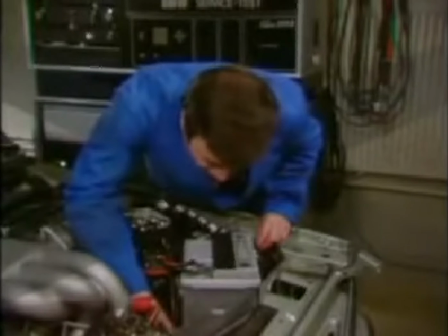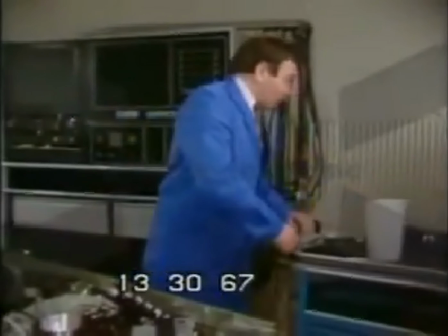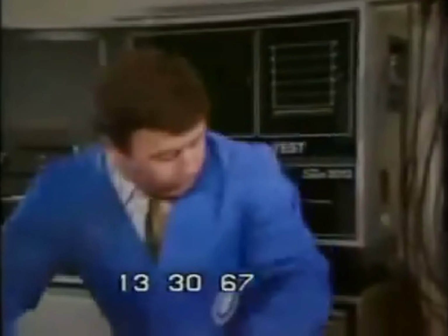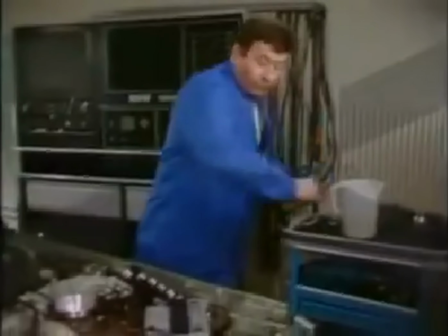Then we check the fuel flow quantity. We want to know if enough fuel is being supplied to the mixture control unit. The tools required for this task are this petrol pipe and a measuring container of about 2 litres capacity. The pipe is attached to the return line of the fuel distributor. In order to bring the fuel pump into operation when switching on the ignition, detach the fuel pump relay and bridge terminal 15 to terminal 87 at the relay socket.